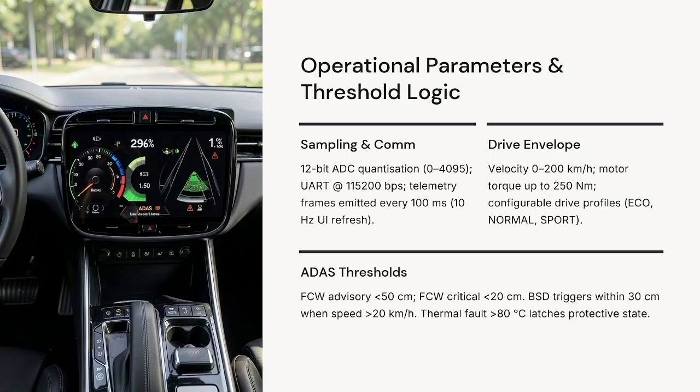And the operational parameters we are using: first, sampling with 12-bit ADC quantization and UART at 115,200 bps, with a telemetry frame emitted every 100 milliseconds, and a drive envelope of velocity 0 to 200 km/h and a motor torque up to 250 newton-meters.